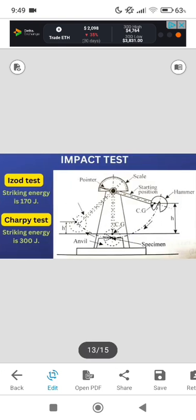Now we release the pendulum. In the Izod test, the required striking energy is 170 joules. In the Charpy test, the required striking energy is 300 joules. It is higher than the Izod test. Now the testing is ended. After that, we will see how the toughness in the impact test is calculated.